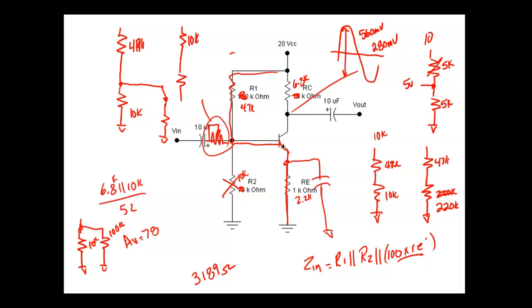Well, it's 9.99999K, right? But as soon as I open that resistor, now here's my current path. So now that's open, and I've got this 220K in series with this, and my whole voltage divider is gone. You see that? So now my voltage is double, right? You understand that? I'm sorry, 22K. It's not 20.